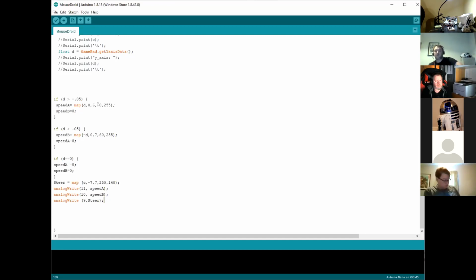You know, if I put that to 254 or 255, it would literally go from 0 to wham. There'd be no ramp up. So again, it's just experimentation really to see where you want to push that up a little bit. And likewise, if you're getting something that's going way too fast, you can pull down that upper limit. Yeah, and then because the other one's a servo, your 250 is your hard left, your 140 is your hard right, and then the 195, which is at the top, that is your dead center.